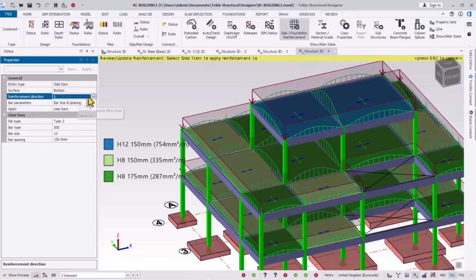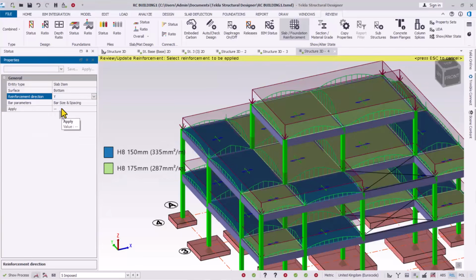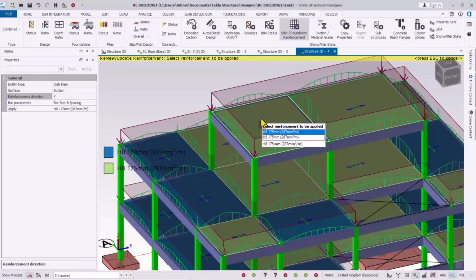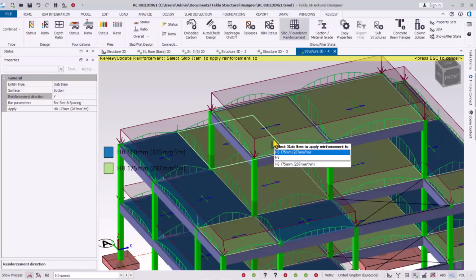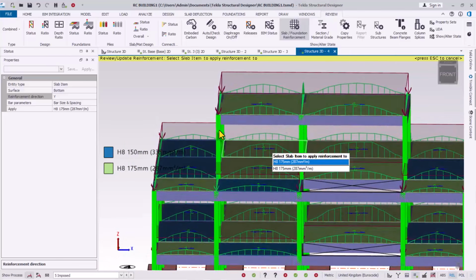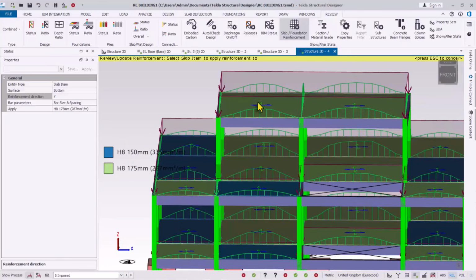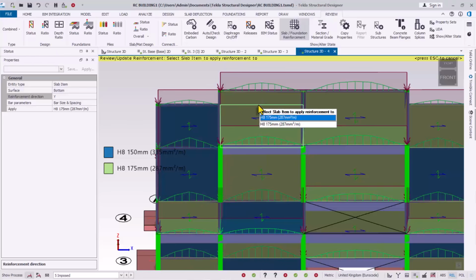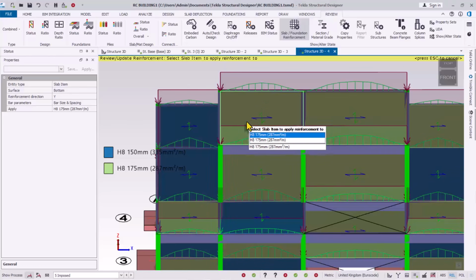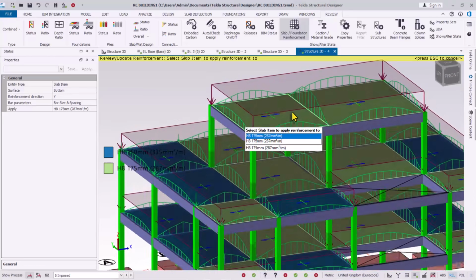So I will select in this provision and change to the Y direction. Under the Y direction, I'm going to be doing the same thing. My concern parameters are the bar sizes and the spacing right here. I'll zoom in closely and pick on this panel right here. Sorry, that is picked wrongly. I want to pick on this panel. Okay, good. I think the panel is selected now.